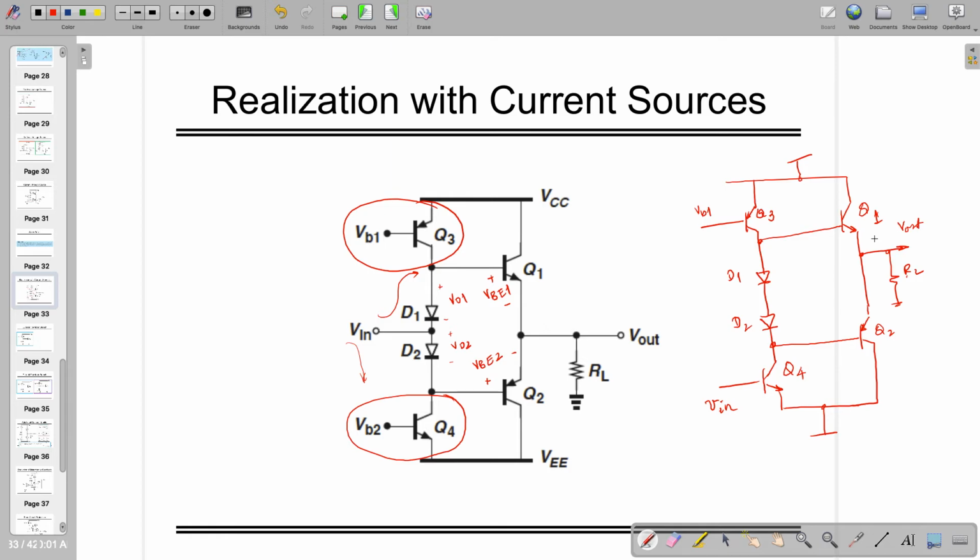So if you are interested in that, what you can do is, if Vout is 0, for that what value of Vin is required, notably, right? So for that we need to have a value which is VB. Both of them, let's call it VB. So it's 2 VB already, right? So you need the potential which is VBE. So you need to find out what value of Vin is going to give you Vout in this case. So you are giving from the downside, right? So that's why it's a positive clamp, right? If it is a positive clamp with the VBE, you need to give minus VBE. Sorry, you need to give accordingly the input value from the characteristic given over here.